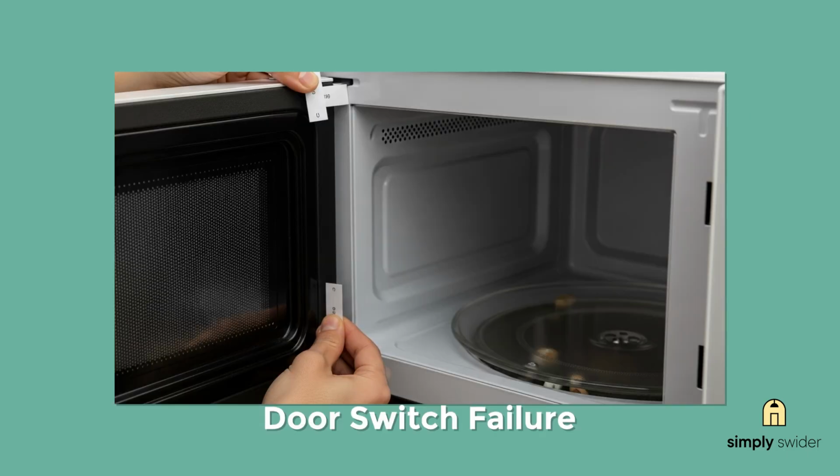Door switches are one of those things that can cause all kinds of weird problems, including the PF code. These little switches prevent the microwave from running when the doors open. It's a safety thing. When they fail, they can cause power cutoffs or even short circuits that blow the main fuse.